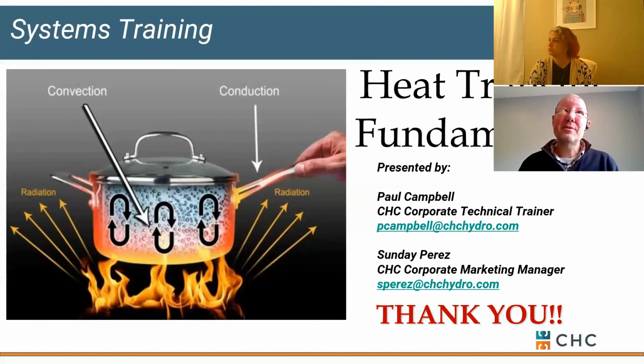If you're looking at a shell and tube, a good rule of thumb there is a Reynolds of 2000 or greater. So a lot of times we'll lock in the heat exchanger, and then we'll look at reducing flows until we get to a Reynolds that's down around 2000, and that's kind of our minimum flow rate. A plate and frame, the Reynolds is about 150. So we'll do the same thing. We'll lock in our plate counts and drive that flow rate down until we get near a Reynolds of about 150.